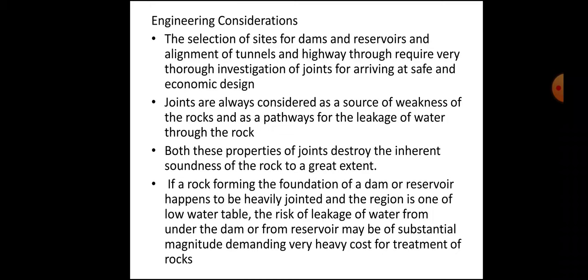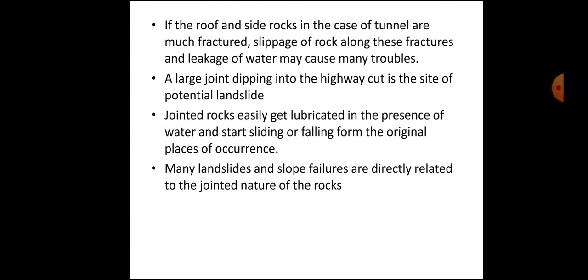If a rock forming the foundation of a dam or reservoir happens to be heavily jointed and the region is one of low water table, the risks of leakage of water from under the dam or from the reservoir may be of substantial magnitude, demanding very heavy cost for treatment of rocks. If the roof and side rocks in the case of a tunnel are much fractured, slippage of rock along these fractures and leakage of water may cause many troubles.